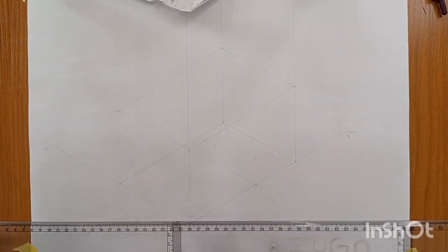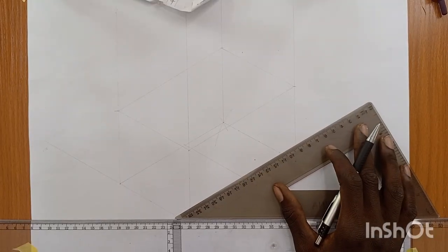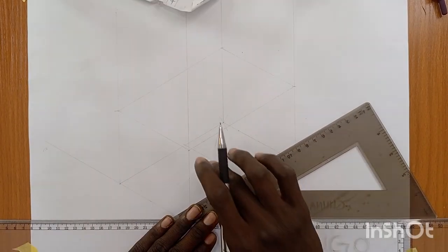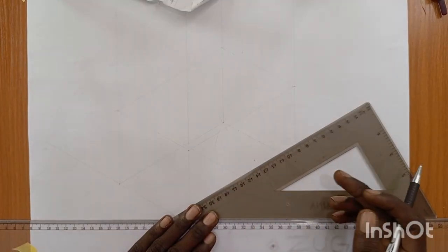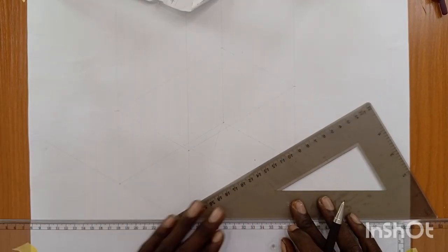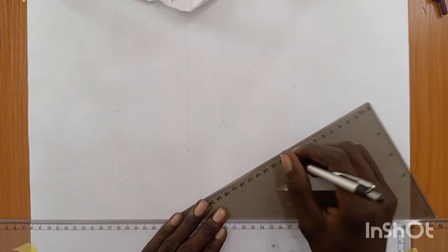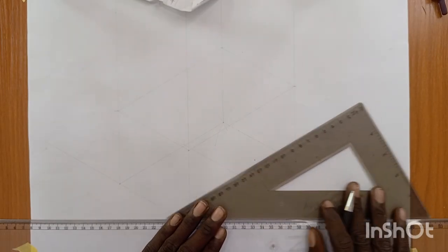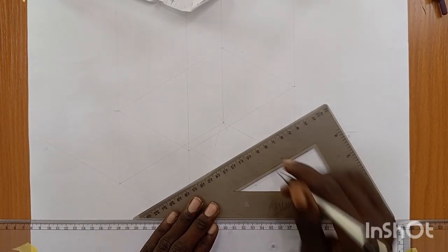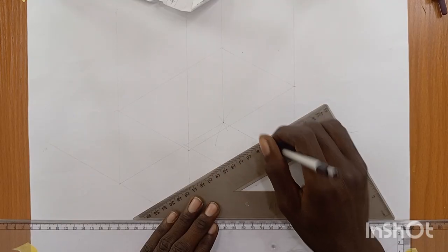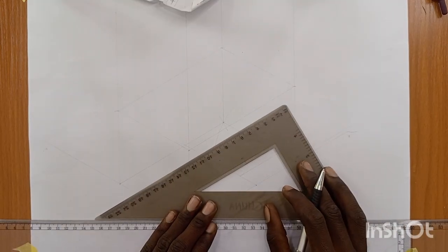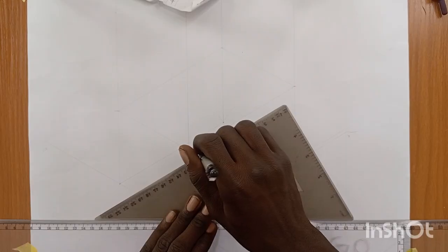Now, the next thing to do, you see that this square is going to be at the center. Now, you carry your 30, 60 set square and make it. If you wish, you can measure the same thing, divide this into 2 and still make 25 up and down. Then you use a ruler and strike if you don't have a set square. But if you have it, to be a little bit easier, then you just run this point and then strike here. Then you come for this one also, the middle one, and then you strike. You may not even need it. For the middle one, you just make a sign here. That's this divided into 2. And then for this one, you now strike it like this.